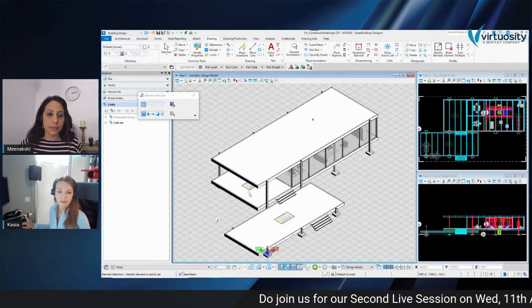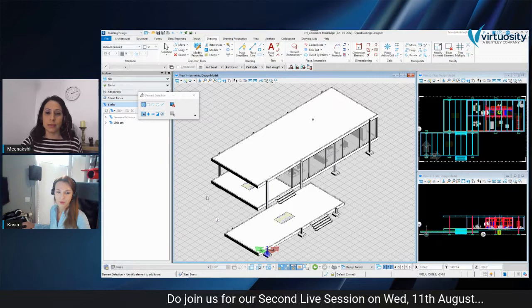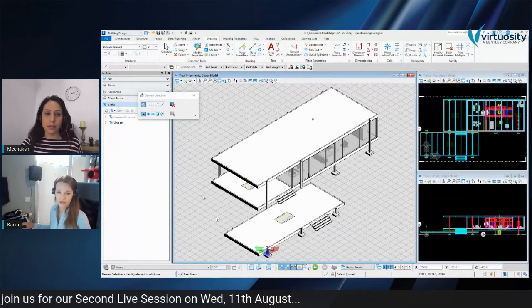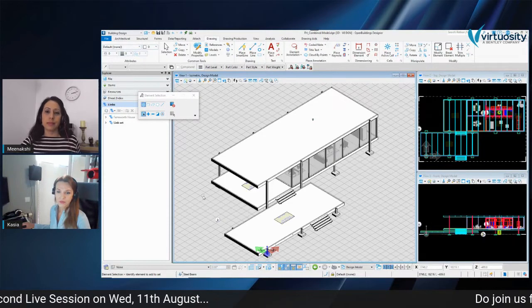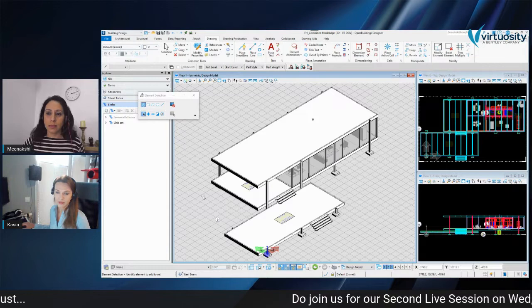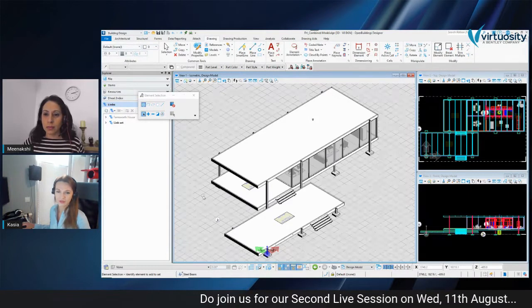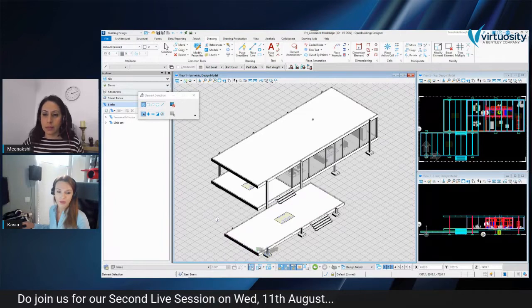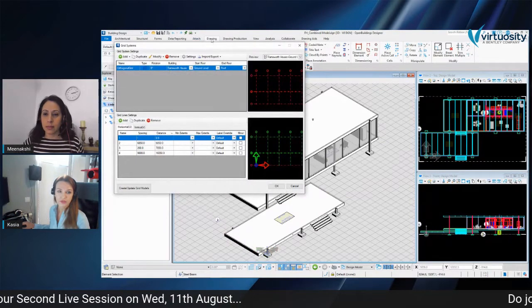Yeah, so the first step would always be setting up a grid system and the floor manager. These two elements are really important during our work on a project. It also makes the work much easier because we get first the structural grid.